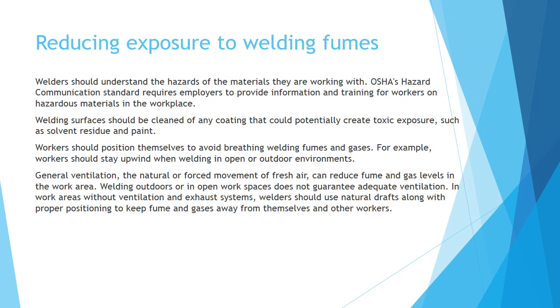Welders should understand the hazards of the materials they are working with. OSHA's Hazard Communication Standard requires employers to provide information and training for workers on hazardous materials in the workplace. Welding surfaces should be cleaned of any coating that could potentially create toxic exposure, such as solvent residue and paint. Workers should position themselves to avoid breathing welding fumes and gases. For example, workers should stay upwind when welding in open or outdoor environments.